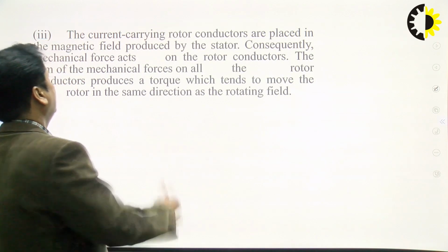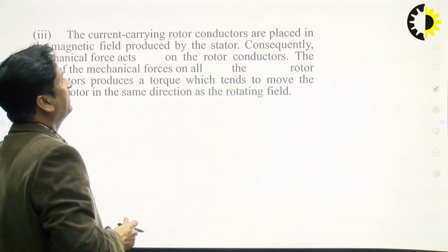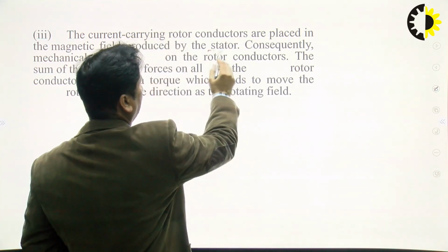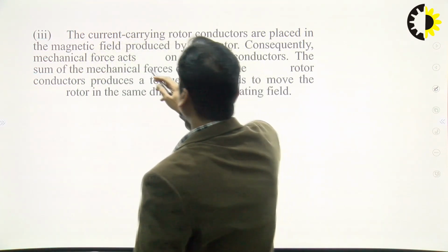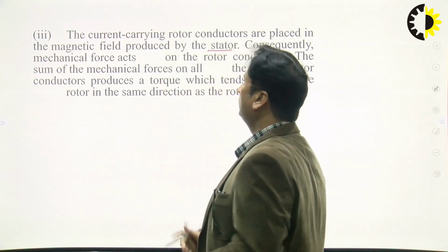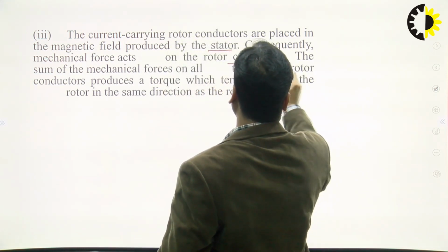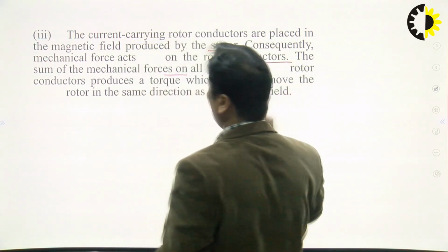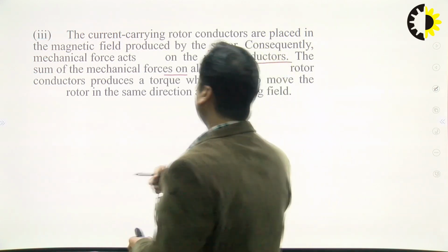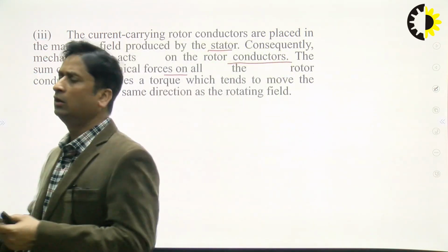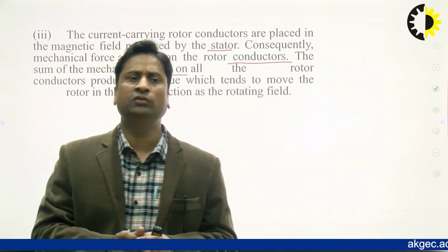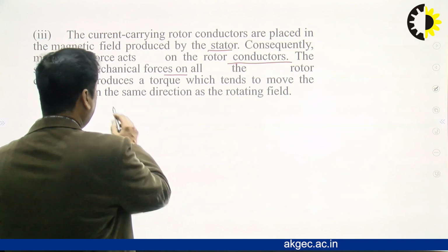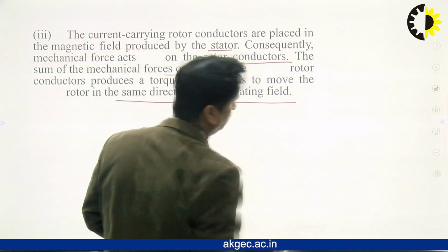We know that the current-carrying rotor conductors are placed in the magnetic field produced by the stator. Consequently, a force will act on all the rotor conductors and produce a torque, which will tend to move the rotor in the same direction as the rotating field.